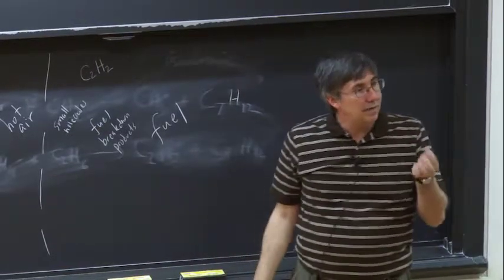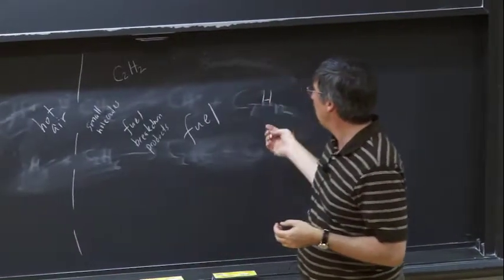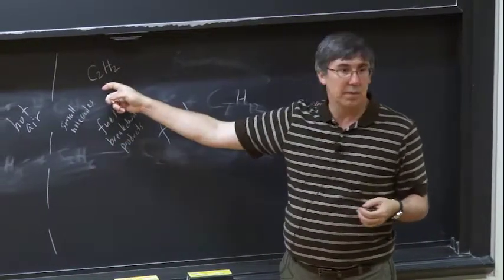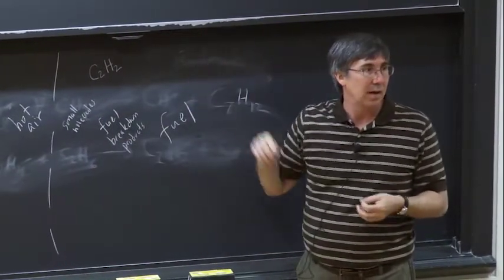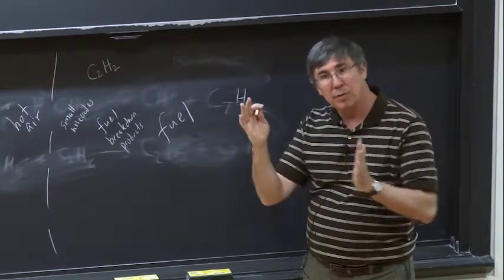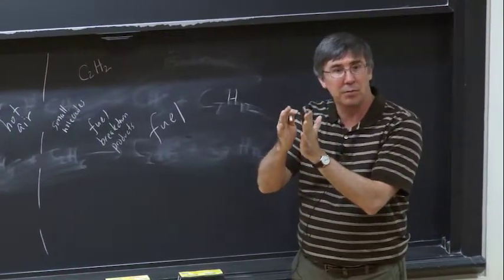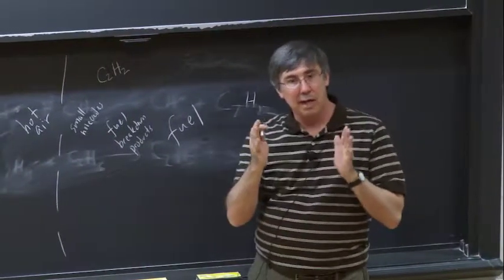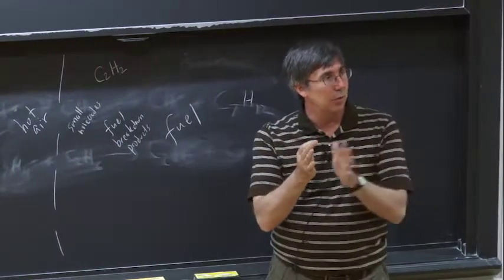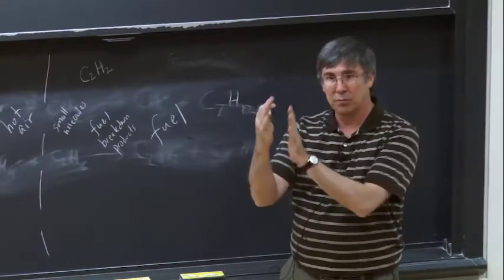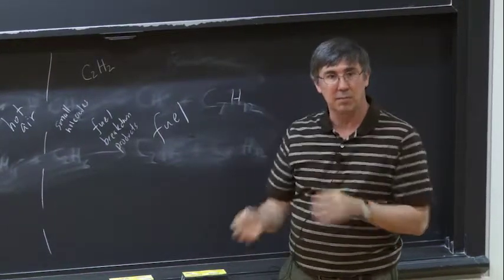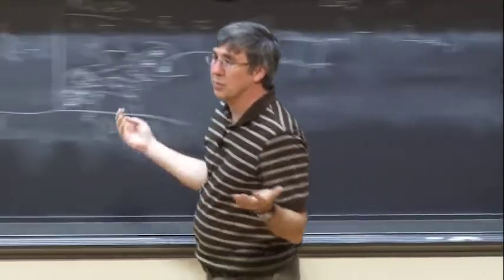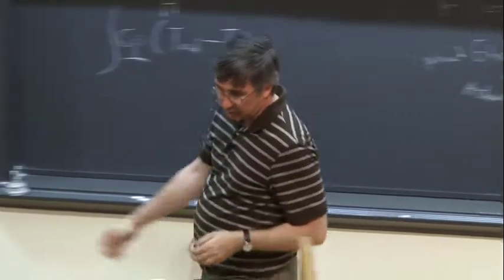So you've reacted the wax. What actually happened was the wax molecules broke down into small molecules, and then the small molecules formed acetylene, and the acetylene polymerized back up and formed all the way up to soot. All that happened before the hydrocarbon got to the flame front. In a very thin zone near the flame front, in that diffusion zone, the chemistry is happening so fast that the fuel can completely break down and get all the way to soot before the stuff gets to the flame front. So if we want to understand this, we really have to think about the pyrolysis chemistry.